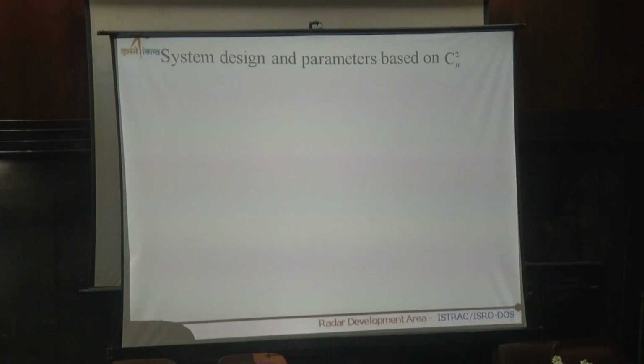You have to match these conditions, bring the blocks together properly, and see that there is no contaminated signal and no higher order spectral or frequency components coming in, because the signals we are looking at are very, very low. Probably what you transmit, say 1 million, you get 1/1000th of that power back, and you have to extract it. That is the concern of a signal processing person. How do you extract such a low level signal without it getting contaminated by the noise around it, and make sure that the detection is correct? Otherwise you make a lot of errors, or your interpretations in the scientific arena get lost.